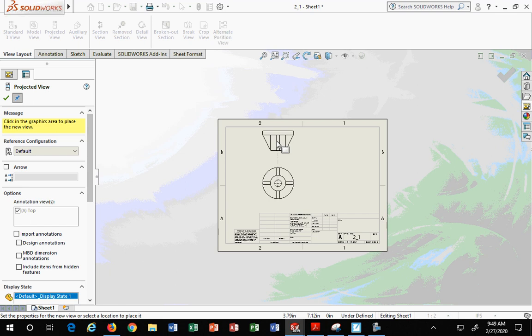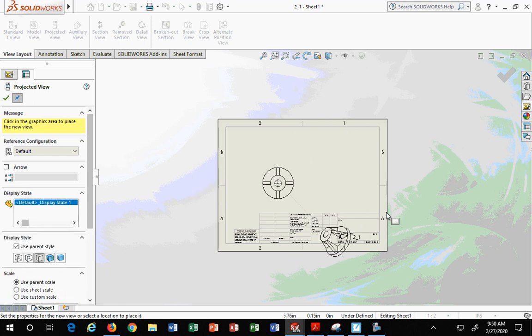Okay? When you had hand drawing class with me, I told you guys, be lazy. Only put as many views as you need or as few views as you can get away with. Get it? If I could get away with a one view drawing, I'm doing it. In this case, I can get away with a 2-view drawing. One is the front view and the other one actually will be the sectional view. I know products like Solidworks, Inventor, all of them can allow you to become lazy or sloppy, not lazy. I'm going to say sloppy for this one. Because you can add views all day long, and I can have 100 views for something that only needed 1. Don't do that, please. Okay?